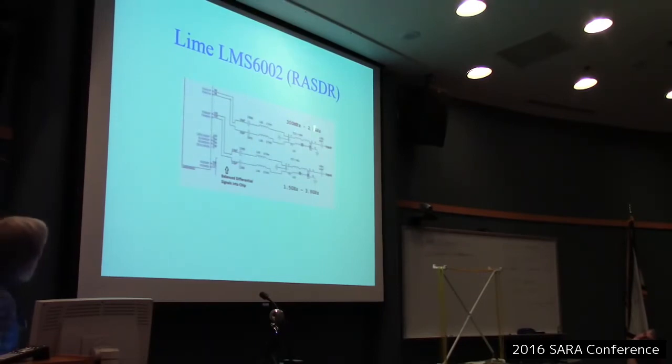Now, if you look at the Raspberry board, instead of a balun transformer type of thing here, they used dual pi networks, one low pass and one high pass. I say that as a mixed blessing. It's got less loss than the ferrite transformer, but it also could mess up your balance a little bit when you get away from the center frequency where the pi networks were designed. So, well, that's a Raspberry problem, when those guys are investigating that sort of thing.